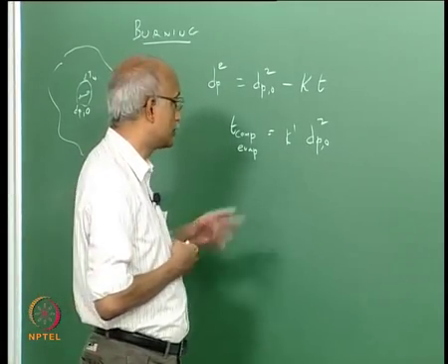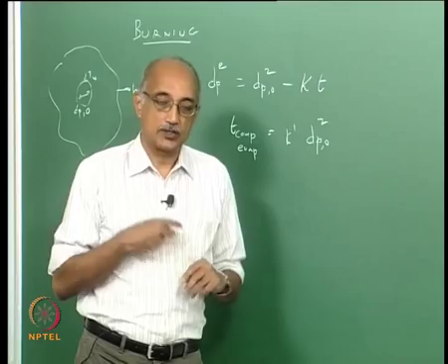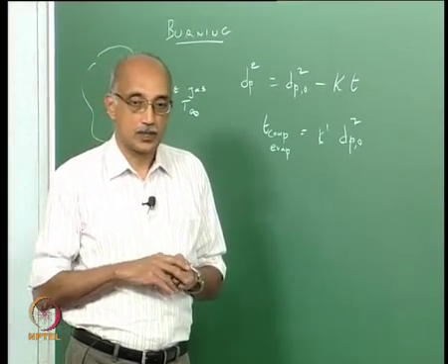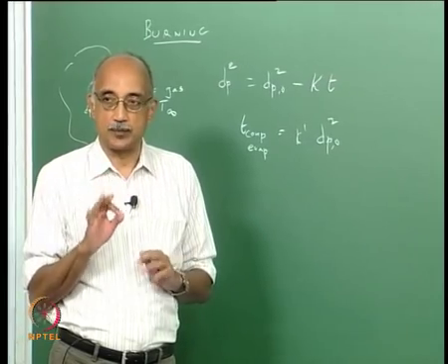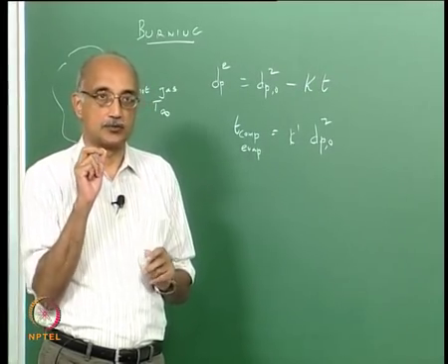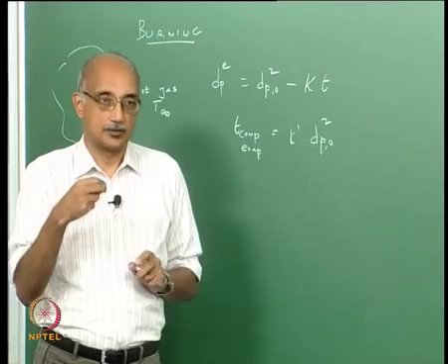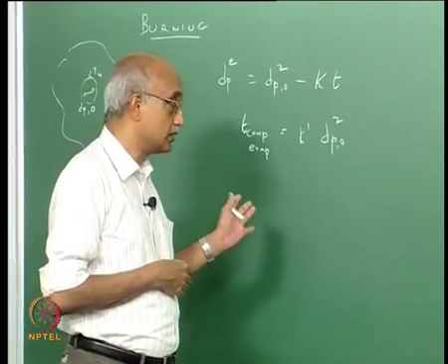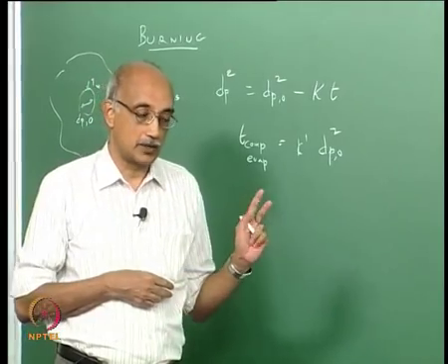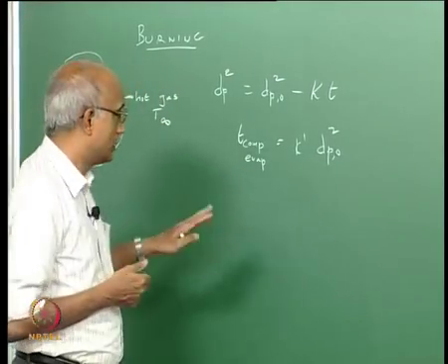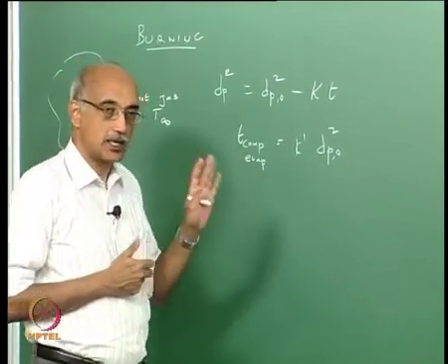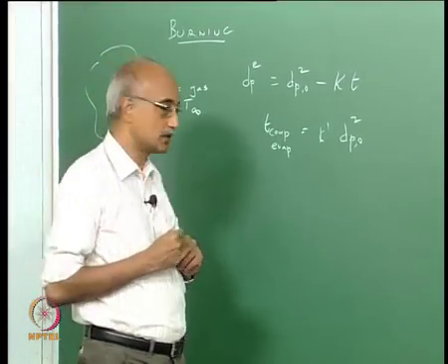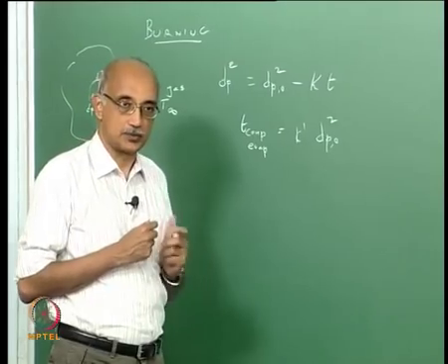So, there is a huge benefit to be had if you are trying to speed up a combustion process or an evaporation process or a burning process. There is a huge leverage in the size of the droplet. The finer the droplet size or the finer the solid particle size, the faster it burns. Now, this expression is something that we are all familiar with, but we need to spend a little bit of time understanding how we arrive at this expression. I mean, what is the underlying mechanism that causes this type of relationship to happen?